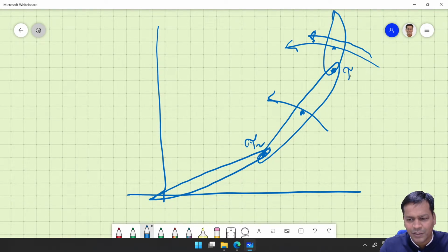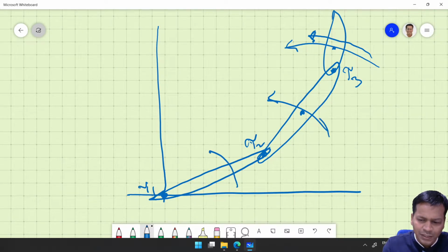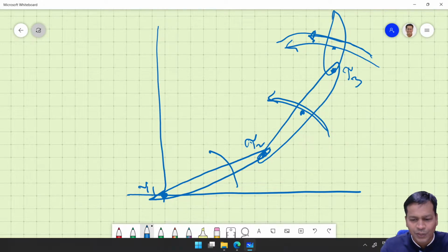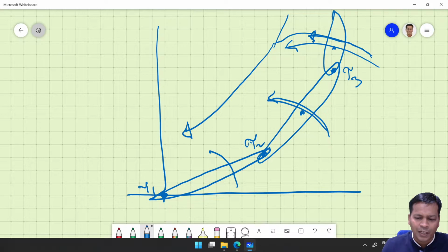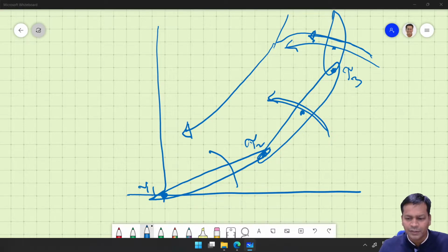If this is tau 3, this is tau 2, this is tau 1, those are the torques. So what is the torque which is here? It is due to the combined motion of this as well as this. So that is a backward recursion. Things are not that trivial as it appears. Definitely in case of 3 dimensions, it is not just the torque, it is the moment that comes, and finally we resolve them along the axis to get the torque. Because it is planar, it is so trivial. So that is what backward recursion is.